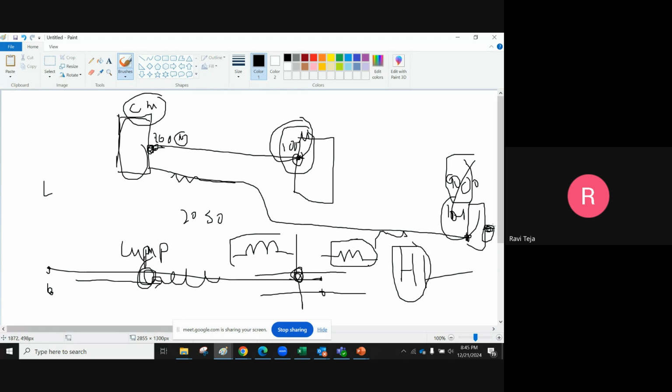So as a layout engineer, what we will do is check these critical current nodes, and place this block in such a way that it is very close. If it is a current net, we will try to reduce resistance or drop on these nets. So yeah, that's what we will do.